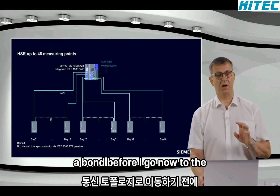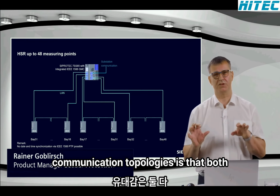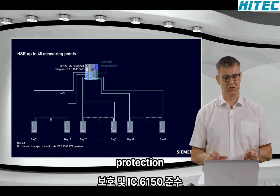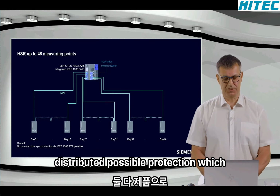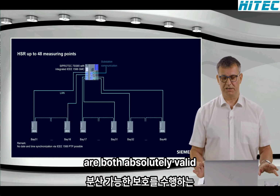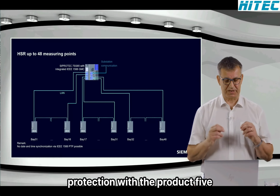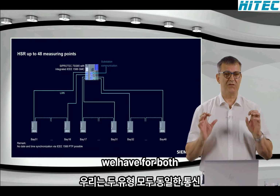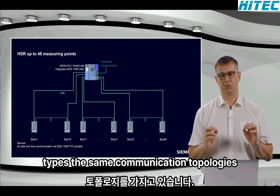Important, before I go now to the communication topologies, is that both for the fully distributed busbar protection and for the IEC 61850 compliant distributed busbar protection, which are both absolutely valid ways of doing distributed busbar protection with the Protect 5, we have for both types the same communication topologies.